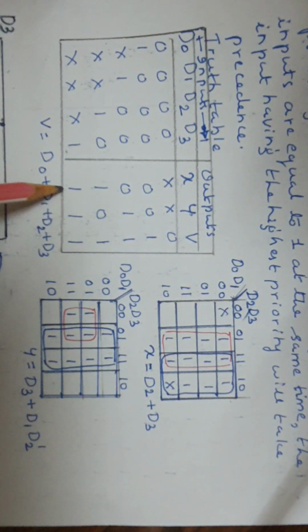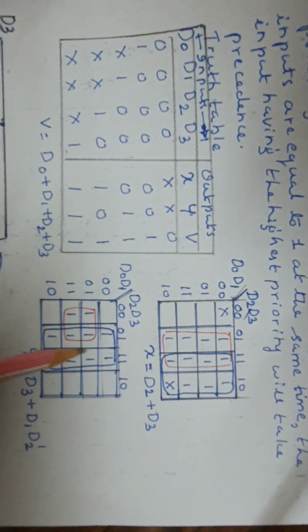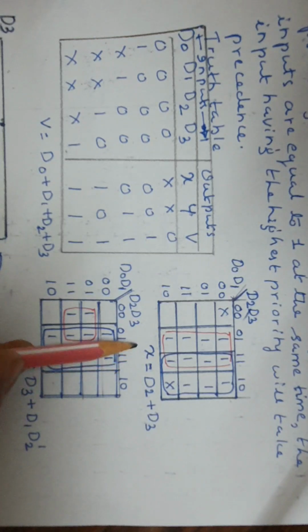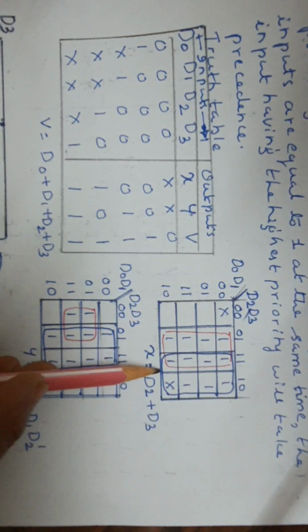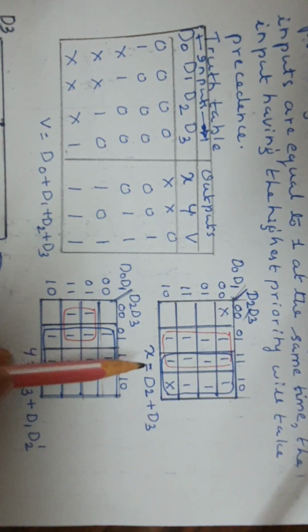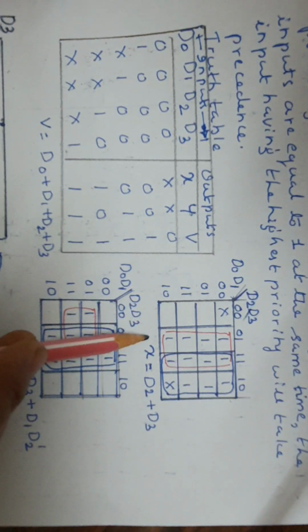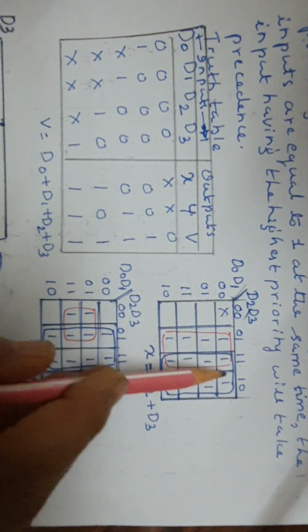In this manner the K map is filled for the other one also, hence instead of only 2 ones, we have many ones. Similarly for the Y output here. After drawing, we group the ones and find the simplified expression. For X, a group of 16 ones we cannot draw, so 2 octets are possible.